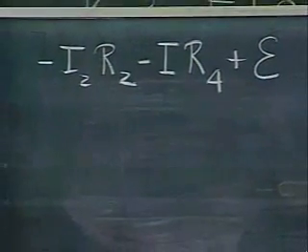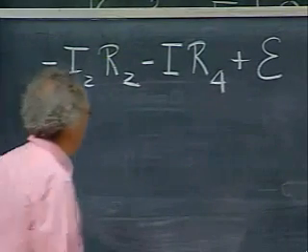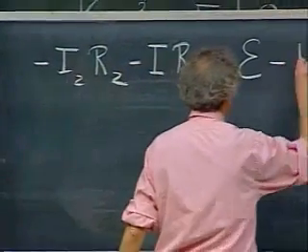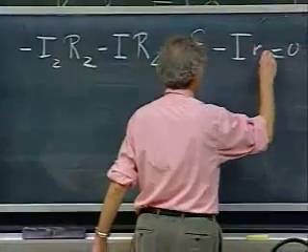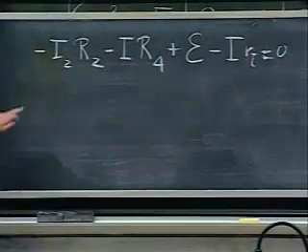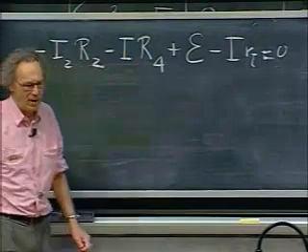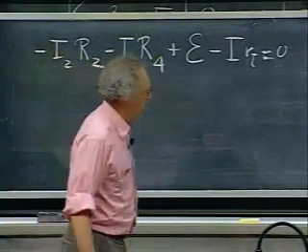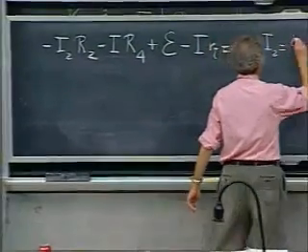But that dinky toy little resistance R of I makes me go down a little bit, and so I get another minus I times R of I, and that now is 0. That's one equation with only one unknown, which is I2, because we already have I. That's the 2.15 amperes. And so you'll find now that I2 becomes 0.6 amperes.